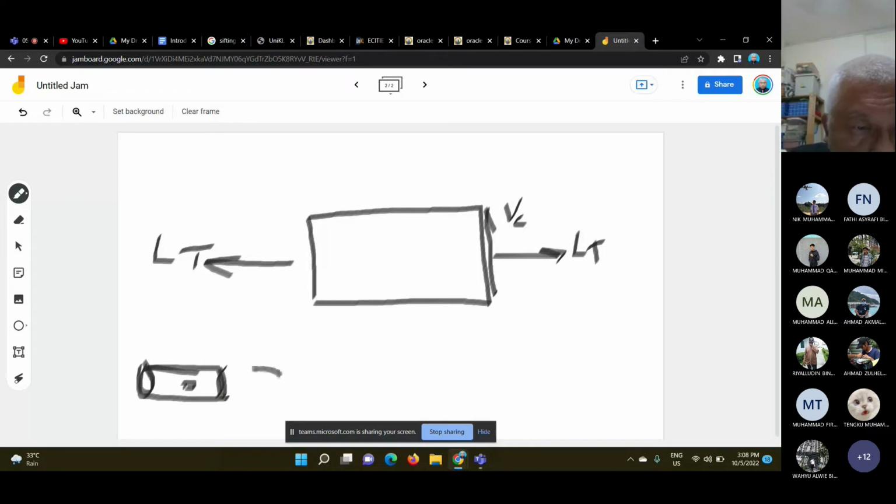When you talk about diameter, you have pressure inside the aircraft, and the aircraft barrel, you can consider it a tube or barrel, whatever, will expand. As they expand, we have tension along this diameter, and we can consider that as a radius. That's why I said radial or circumferential. Circumferential is something round.